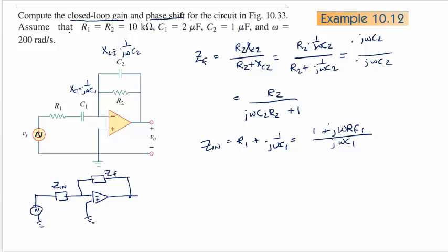So closed loop gain is basically our V out over V in. V out over V in is closed loop gain, and that's often given the symbol G for gain, not to be confused with susceptance. So the gain of this circuit, closed loop gain, which means the feedback is connected up, is just from recognizing that that's an inverting amplifier. Oh, shall we go through the whole derivation? Let's go through the whole derivation. Your textbook didn't do it, but let's do it, just for the fun of it.